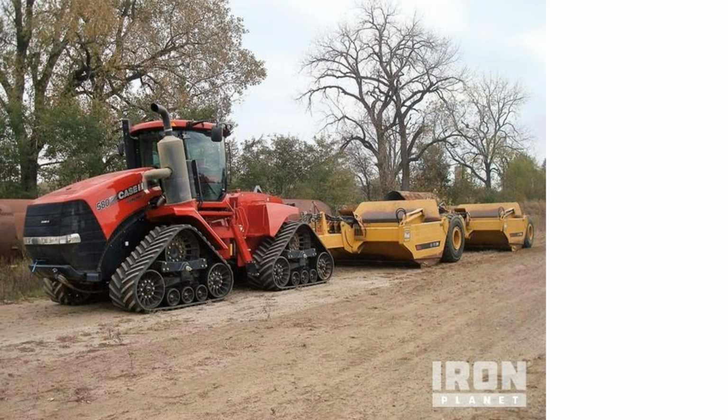Of course, we have the right tractor with lots of motive force. We can have it haul 2 different vehicles. And you can see here where there's a little bit of rust that these vehicles are engaged in active work, so you can see rust marks and you can see scraping here. So these are wear parts. This cutting blade often needs to be replaced, and the hydraulic controls from this tractor are in fact controlling the scrapers. This vehicle may do quite a bit of additional work, and you could figure out what the loading characteristics are, or what the resistance to load is, and figure out whether you have sufficient drawbar pull in order to keep things working.